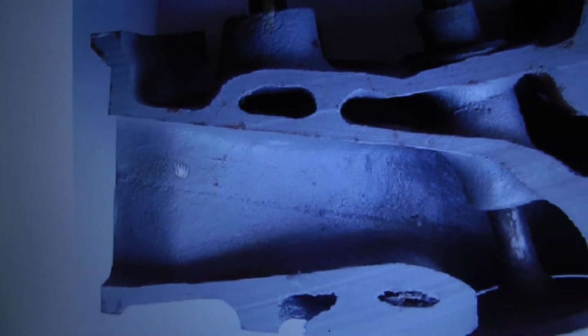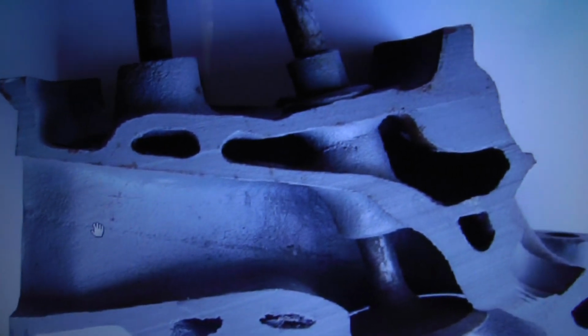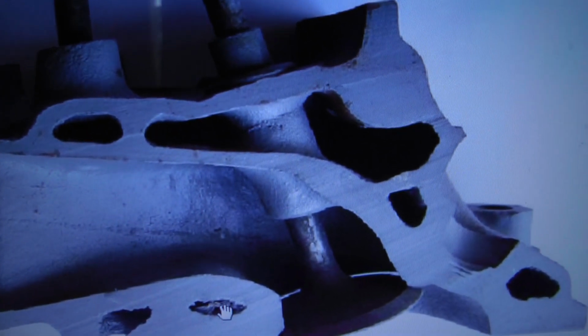Maybe if you're opening up the ports or going around, you can kind of see the push rod bump here, which this isn't a good way. You'd have to see it at a different angle. This is a water jacket here, and a lot of the airflow is opening up the bowl. Again, no more than like 85% or so of your valve face that you want to open this bowl. And then here's the guide boss from a cross section, and this is the short turn radius. You're doing a really bad job if you open up that water jacket. You don't even really need 50% of that, if that, maybe 35% taken off. It's really more about reshaping it than opening it.